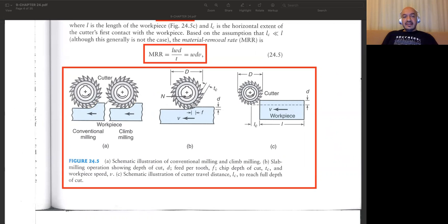So I can say that since these teeth are actually facing the dirty surfaces, unmachined surfaces, so the quality of this unmachined workpiece highly affects the life of our cutter. So it's probably there are lots of dirt on the surface, and once you're hitting on the surface with your teeth, then it may harm your cutting teeth and may make them dull actually, and you need to do some resharpening operation frequently.